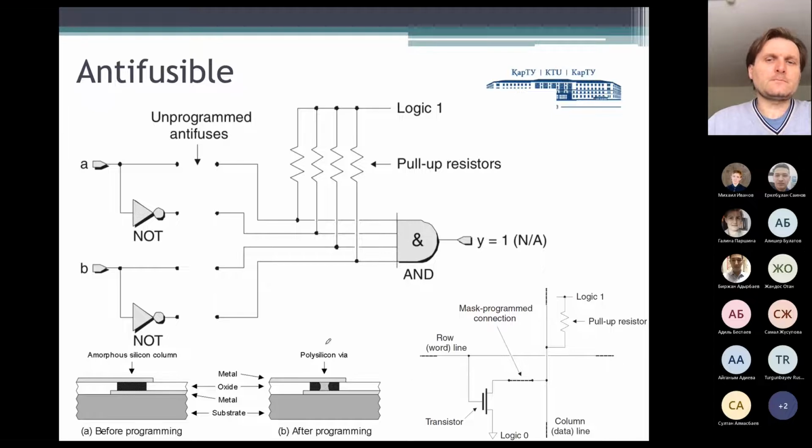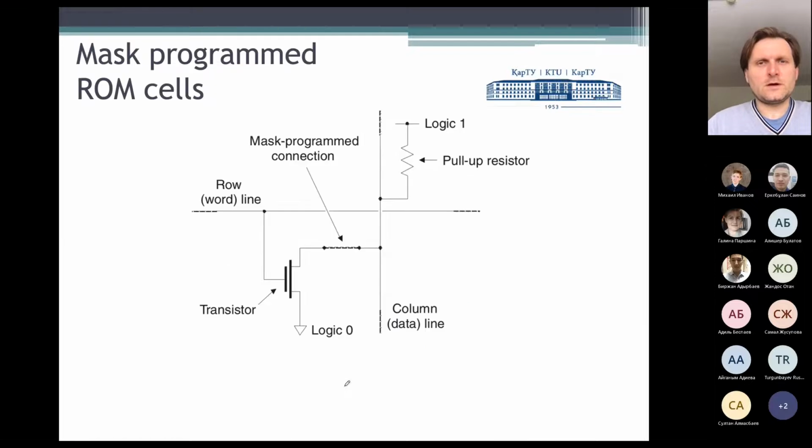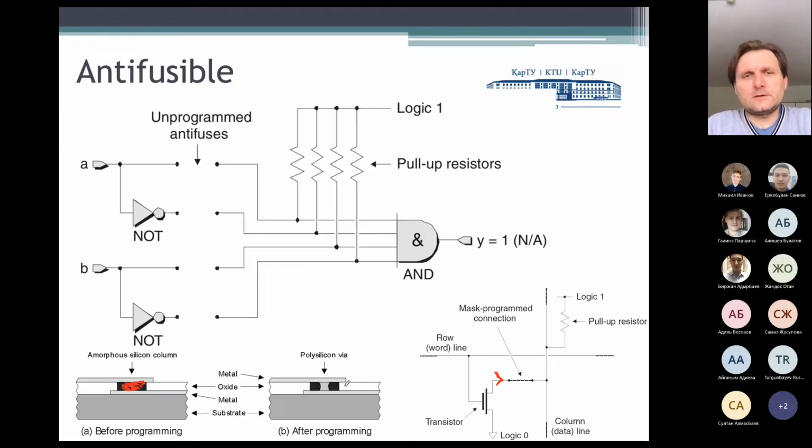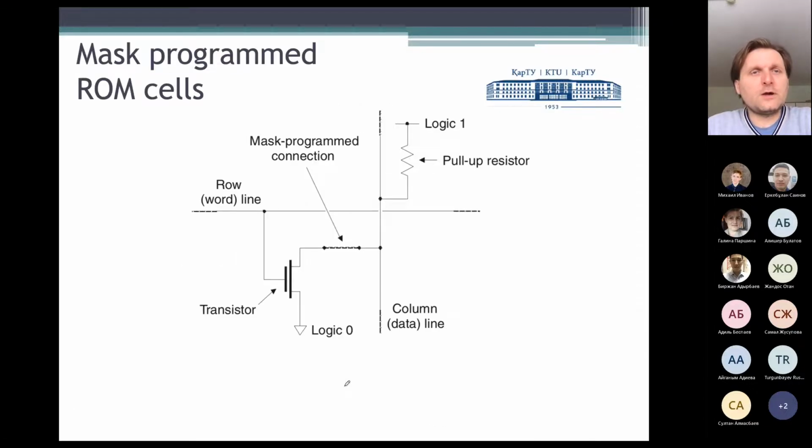Anti-fuse is the technique which I mentioned on the previous screen. The structure before programming is this. There is a connection here. After programming we have a gap. Of course, when we would like to program that anti-fuse and fuse structure, we put a mask, and based on that mask we change the physical structure of that integrated circuit. We should design that mask, we should design the properties of that mask, and for the properties of the mask we should design the circuit, and we should test that. That's it.